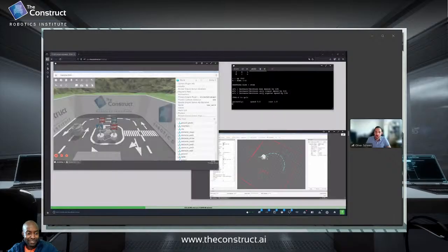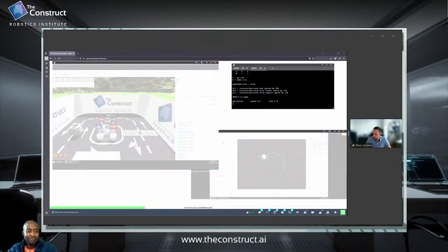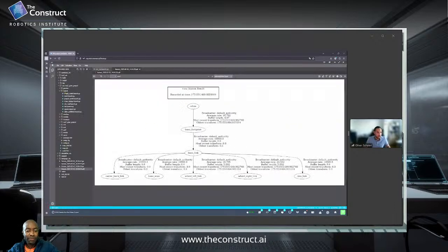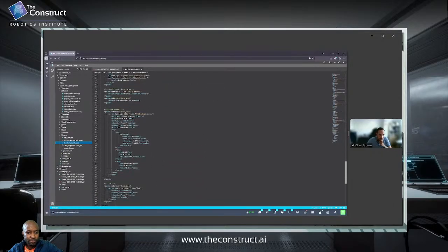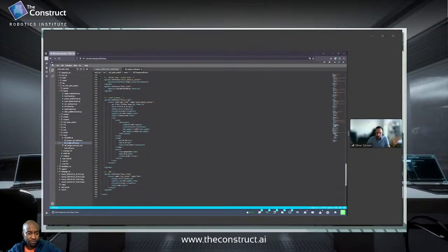Yes, so when I mentioned the difficulty of the performance of Gazebo, the second major difficulty I had was the laser scan data, which was not exactly the namespace, but more the frame. Let me quickly go into the files here. If we go to the robot Xacro file, I have the laser scanner down here, where we have the Gazebo reference, base scan, which is the frame. Then it says the sensor type and the name, this head Hokuyo sensor. What I didn't do is define this Gazebo frame ID. When this was missing, it was still providing the laser scan topic, but the frame was a kind of concatenated thing of base scan and the head Hokuyo sensor and so on.